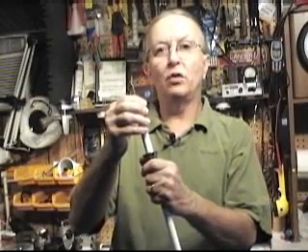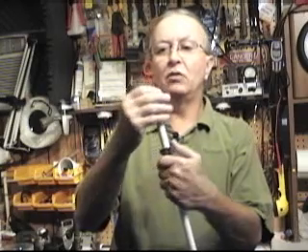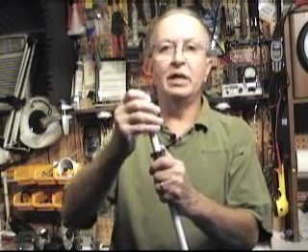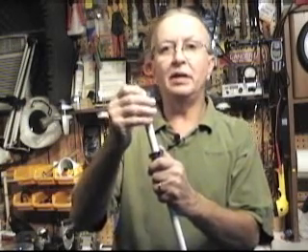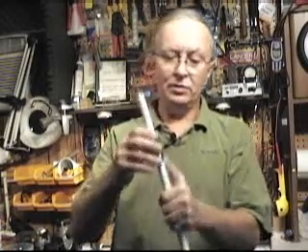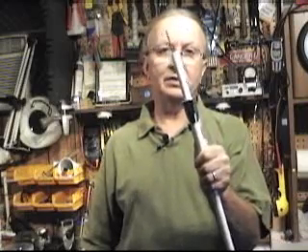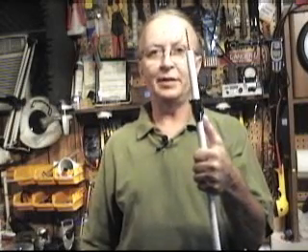You do want to be sure anytime you put up a new antenna or replace an old antenna that all connections are clean, corrosion-free, and everything is good and tight and bonded as best as you can make it. You also want to be sure that you seal all joints and connections on the antenna so that you can keep the elements out. That was a good tip. Anybody that's going to put up an antenna ought to take time and solder those crimp connectors before they put it on. Yeah, they really could. I hadn't thought about that, but our friend Jeff Corcoran, W5PPB, told me about it. That was a real good tip.